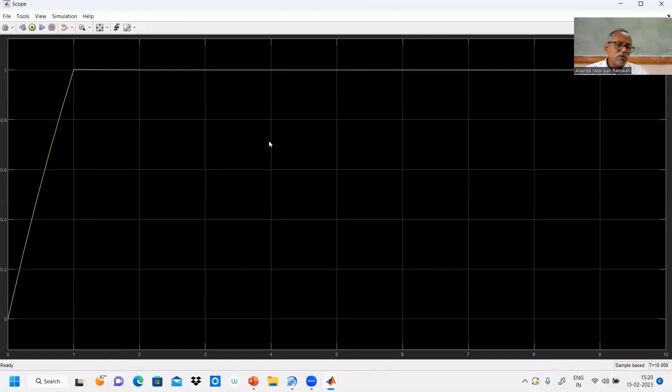So we gave a step change in the input, but the response is settled after one sampling period. What way we designed? We expect the response should be 1 after one sampling period. That is correct. It is settled at 1. So what we designed is that after one sampling period, the response must be 1. It is there. You understand this?